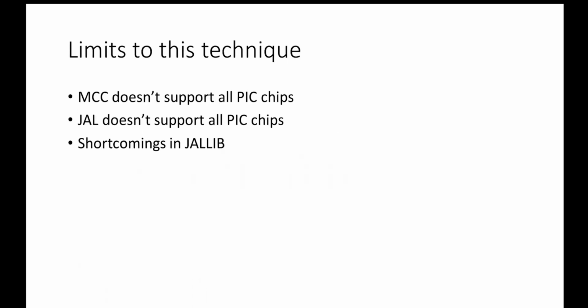First of all, we have to say that MCC doesn't support all the PIC chips, because the PIC chips going back in history had different names for registers and stuff. Everything, the current Q series chips and the two versions before that, MCC will support, so there's no problem with that. If you go back to the old 675s or 877s or things like that, sometimes it was called Port A, sometimes it was called RA, sometimes it was called Tris A, sometimes it was called Trisp A, and all of the register names changed from datasheet to datasheet to datasheet. And so for that reason, Microchip has just cut all that stuff loose, not interested in it.